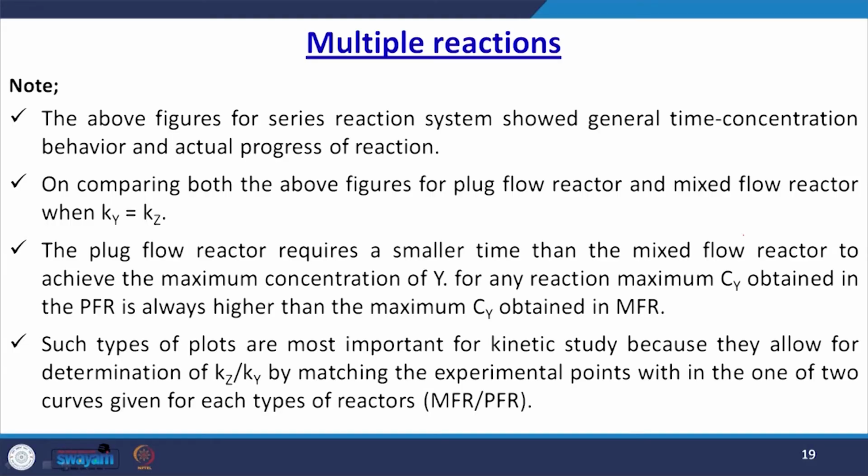Now if we compare these figures for the plug flow reactor and the mixed flow reactor, when Ky is equal to Kz, the plug flow reactor requires a smaller time than the mixed flow reactor to achieve the maximum concentration of Y. For any reaction, the maximum concentration of Y obtained in the PFR is always higher than the maximum Cy obtained in the mixed flow reactor.